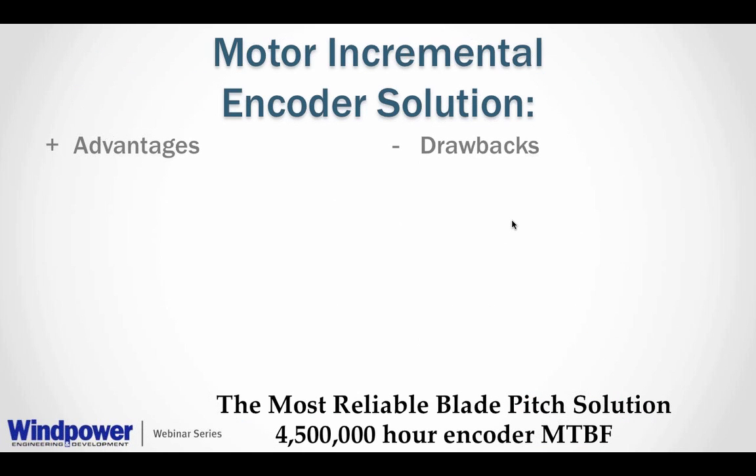So why do we think that picture I showed you earlier of the motor incremental encoder solution is so great? Well, number one, absolute encoders are generally much more fragile than incremental encoders. Most absolute encoders are optical sensors. We're going to talk about the vulnerabilities of that later. They have glass discs. They have plastic gears. They have very small signals generally. They're just mechanically less durable. So incremental encoders on the other side, you can use an optical or a magnetic. You don't have to use a glass disc. You don't have to use gears.